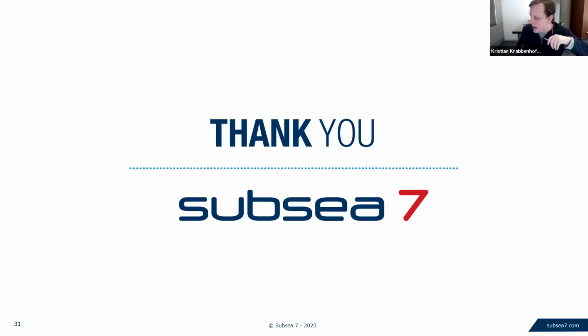Sure. But I think it's fair to make the general comment that interfaces obviously are very important, and that it is more or less convenient to define them. And being an Optum man, I know that this is something we've paid a lot of attention to, and I think it works really quite well. So of course, having a strength reduction at the interface is something that you often do, and also when it comes to undrained analysis, a tension cutoff is something that is often essential, and that's really quite straightforward to do.